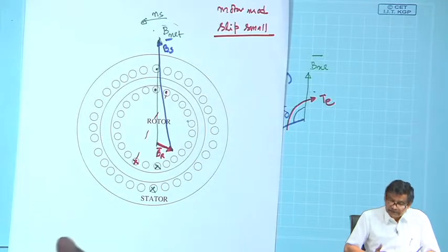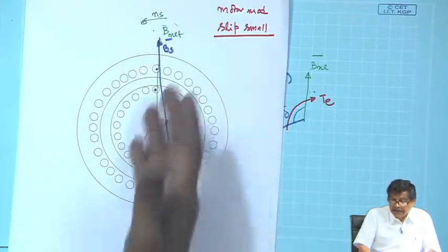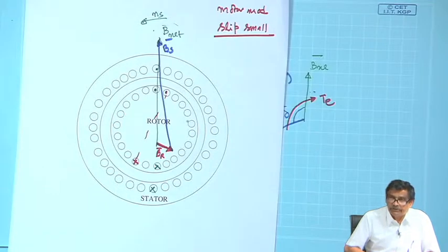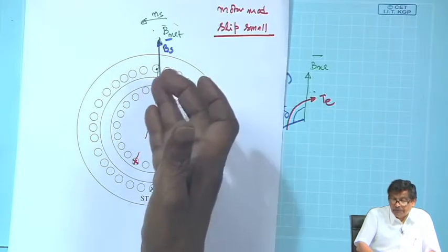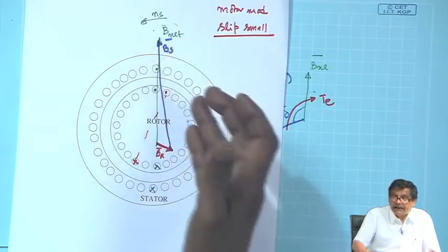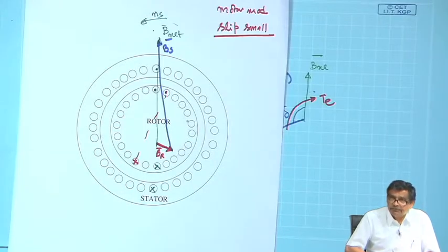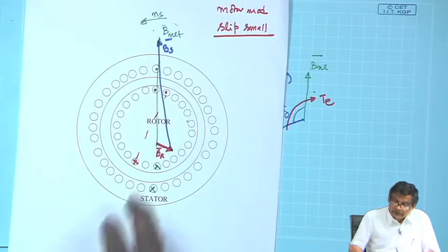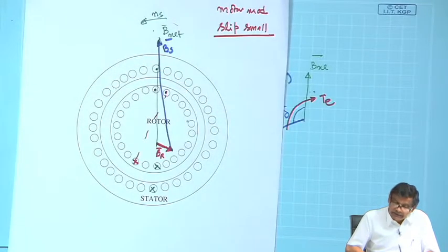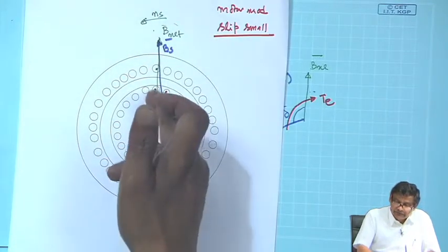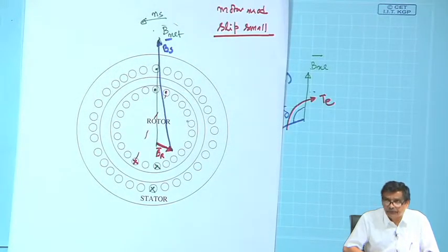For net field, whatever is the induced voltage, in one stroke I can get, because all B are sinusoidally distributed, that is what we have assumed, only fundamental component of the MMF we are considering. Therefore, they will have sinusoidal induced voltage, flux per pole will be 4 pi P B net L R, resultant flux per pole. Then use that famous formula root 2 pi f etcetera to get the induced voltage. And this B net will also decide what will be the induced voltage in the rotor.